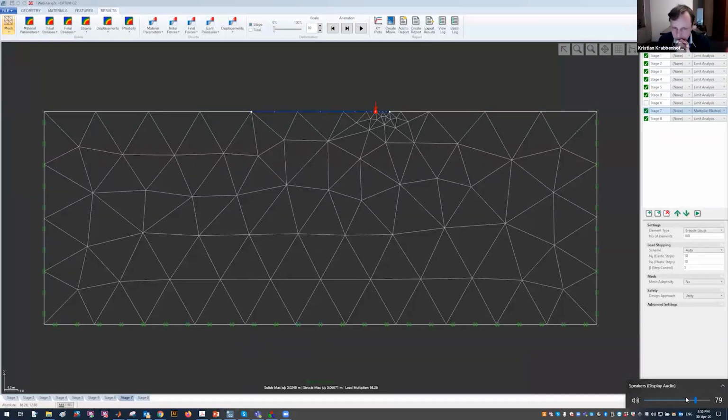Sure. For the first question, limit analysis would not be the way to go. If you want no plasticity, because limit analysis corresponds to a fully developed plastic solution, it would be elastoplastic analysis that you'd be looking at, and that's possible to do as well. So you should have a look at that. And for the second question, with ratcheting, yeah.